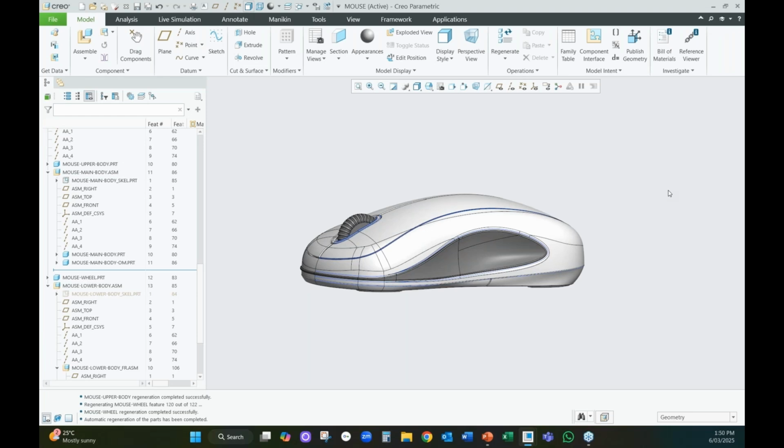One of the big advantages of this is that it works with or without Windchill or a data management system. When you need different people working on the same geometries but without working on the same assemblies, you don't have to have those assemblies in session, so they won't be bringing the whole assembly into session and then saving over each other, and it's whoever hits save last wins. I do recommend Windchill and data management systems, but certainly many organizations aren't quite there yet. So this is a way of managing that. It requires extra thought and thinking, but certainly enables you to do that.